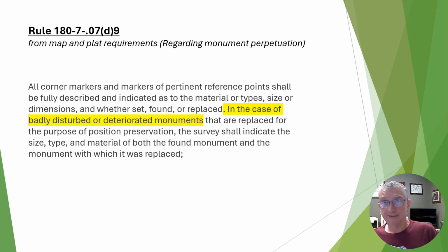I found a rebar. I might need to dig down there and see if there's an open top down there that he missed. The metal detector's not going to give me the answer. Maybe he set a rebar a foot from the open top or a half foot from the open top. The open top's still the corner. Now we've got a pin farm and a problem. But if your survey documents the 5/8, 1/2-inch, whatever rebar, whatever corner you set, at a badly deteriorated 1-inch open top pipe, then you have provided that link. You've got the called for monument of a 1-inch open top incorporated. Now it's where that capped rebar is.